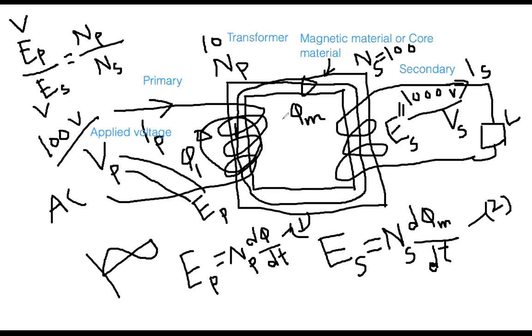On the other hand, everybody see the example. For example, here on the primary side, your number of turns is 100. Now you change the value of NP to 100 and keep the voltage the same. Your EP or VP is 100 here, but the NP value is now 100, and this value, NS, is just 10. You will be getting this time 10 times smaller voltage. It was 100 volt on the left side, but on the right side, you will be getting only 10 volt.